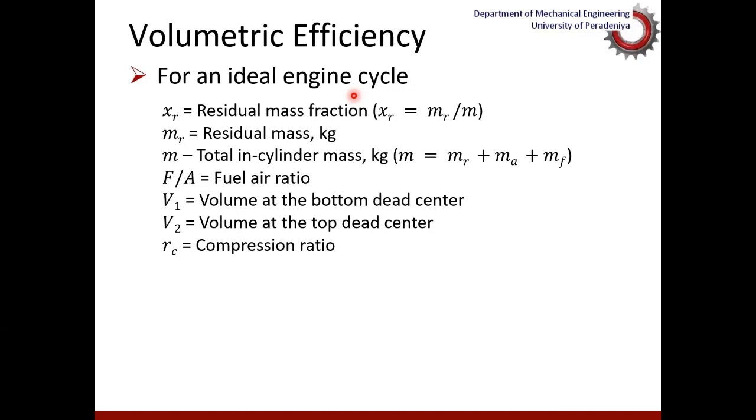That means some amount of exhaust gas is left over in the cylinder at the end of the exhaust process. Therefore, the incoming air is mixed with not only the fuel, but also the burnt gases from the previous cycle, which are called the residual gases. So we could represent the residual mass fraction as the ratio of residual gases to the total mass of the cylinder.